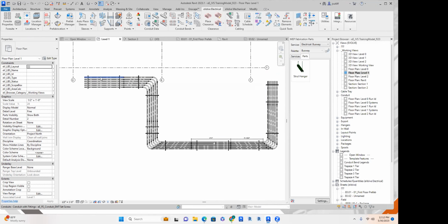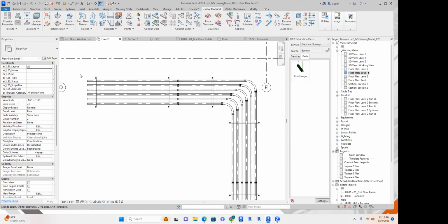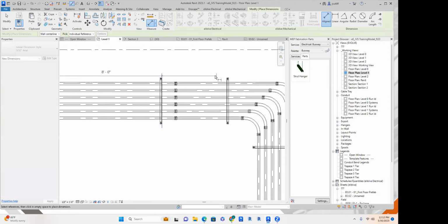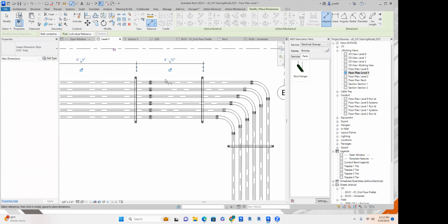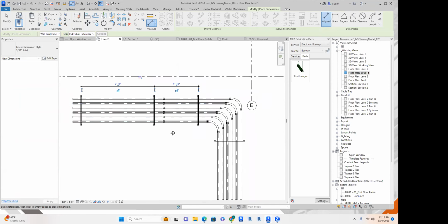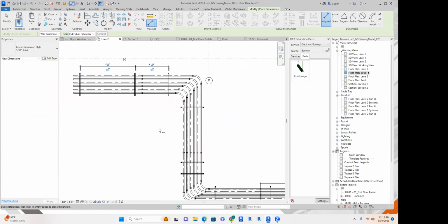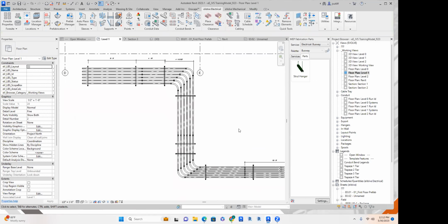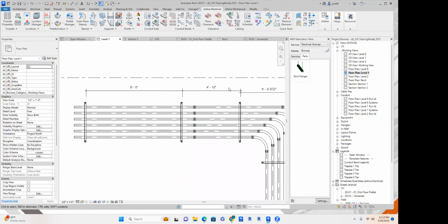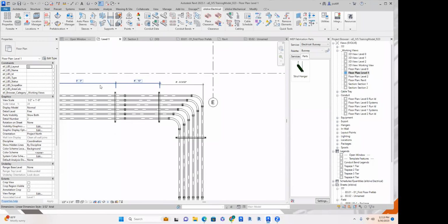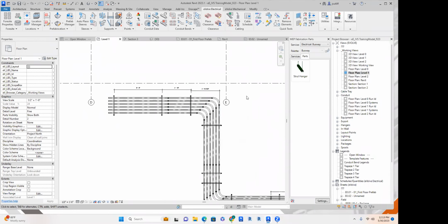And as you can see, we've got our hanger placement in at a spacing of 8 feet, which is pretty typical, so that you've got your spacers or your hangers not conflicting with any of your unions. And will allow us to dimension very easily. And you can see that it placed it at a really good dimension, so you don't have any odd hanger placements that we have here.